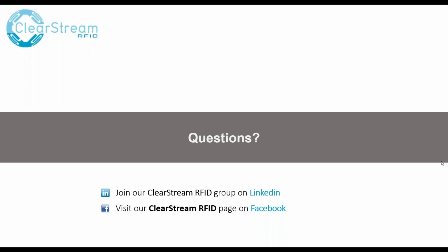So if you had a photo eye at the location and you hook it up to GPI port 1, the only configuration you need to do in ClearStream is switch the scan mode to GPI, set the port number to wherever you have that photo eye installed, and then specify how long you want it to read. So then somebody walks through a portal, they trip the photo eye, it reads for X number of seconds, shuts off, sends all the tags that were scanned to the destination. Hope that answers your question.